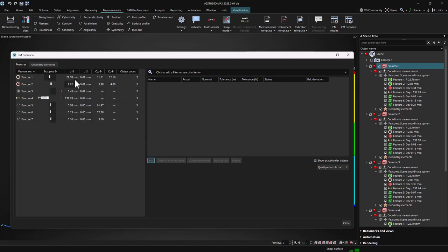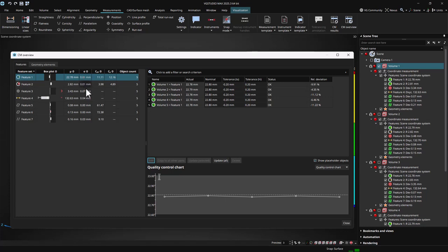Various numerical indicators, like the statistical mean or the Process Capability Index (CPK), are also displayed. Selecting a feature set will not only display a table of the individual features and their properties, but also a plot area where certain properties can be easily compared between the different features in the set. By default, the actual values are displayed, with the tolerance band highlighted in gray in the background. It is also possible to select different properties of the feature for plotting.